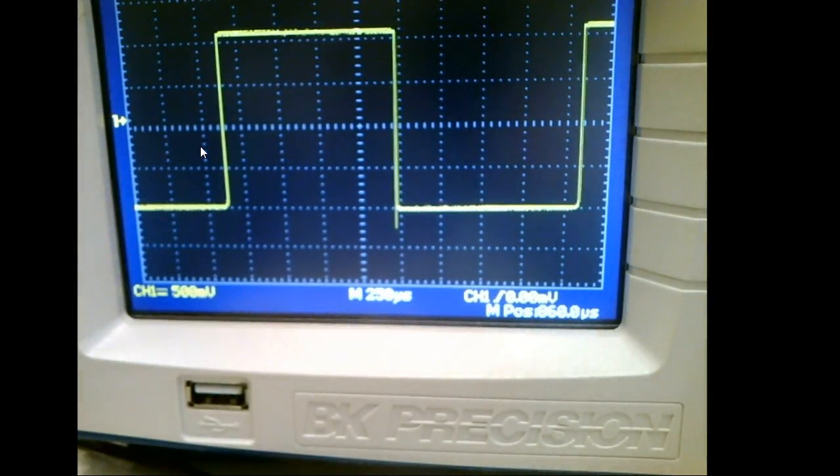So I put less volts per division. This is the best I can do on this waveform: I turn it till I can see one cycle, and then I adjust the voltage till I can maintain it on the screen. That makes sense? Okay. Now my scope is as accurate as it could possibly be.